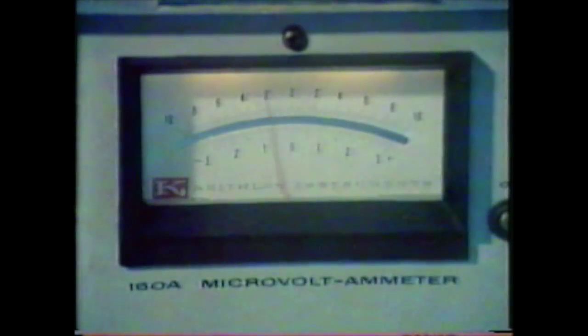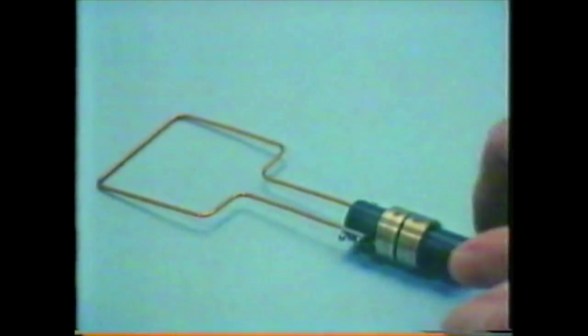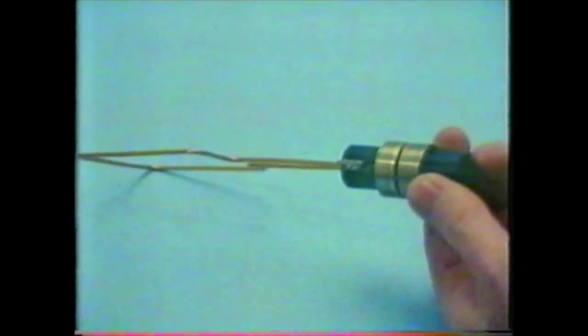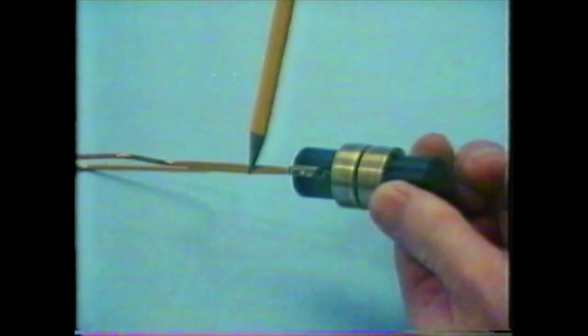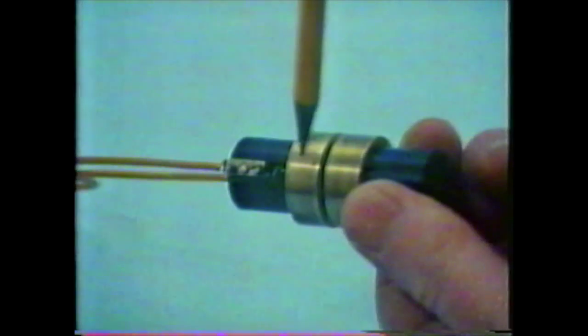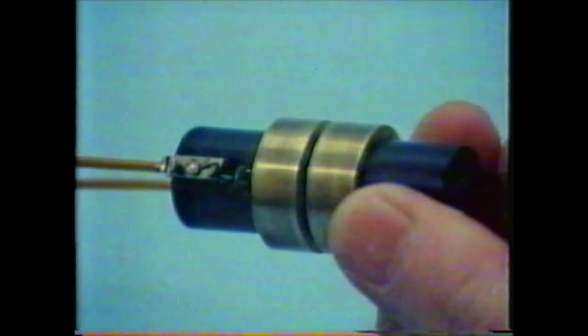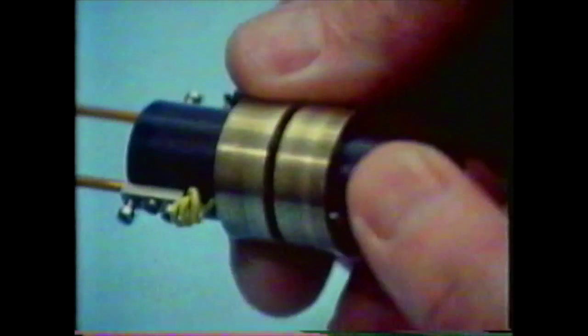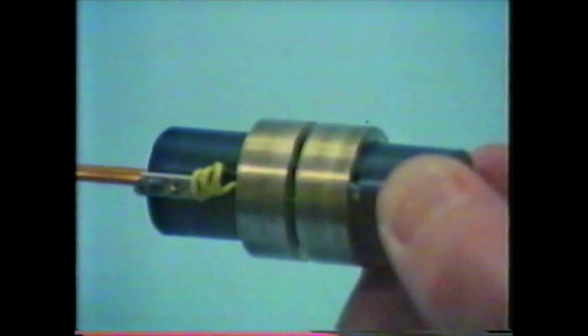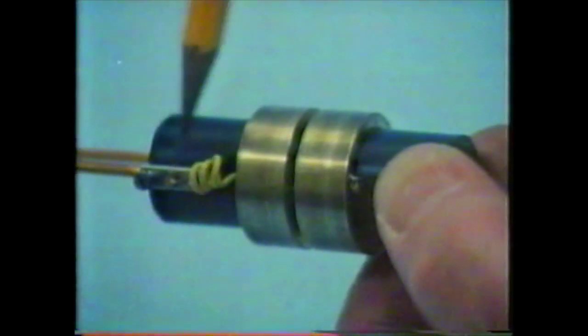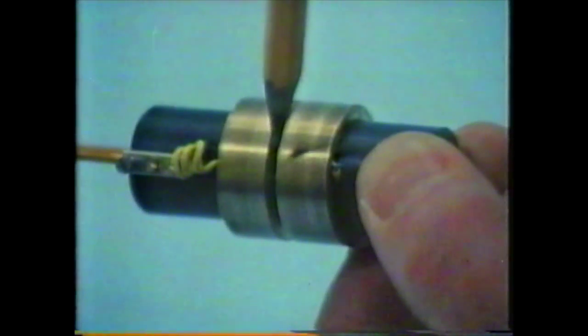Here it is again. Using just a single turn of wire, we get only a very small current, and as we saw before, the wires got all caught up in a very short time. So we can use this device. The same single loop of copper wire, but one end's connected to this copper ring on an insulating spindle, while the other's connected to the second copper ring. The insulated connecting wire passes underneath the first ring, then it's joined to the second one. These are called slip rings.